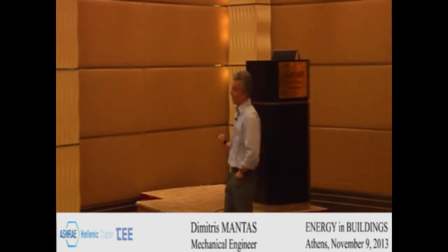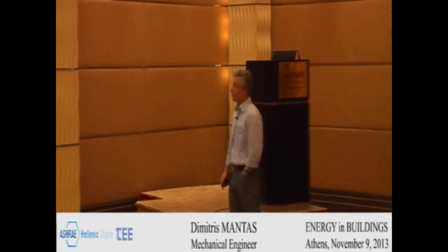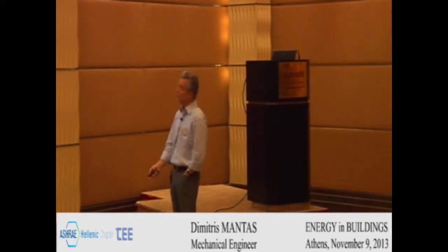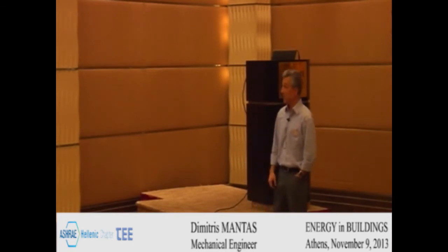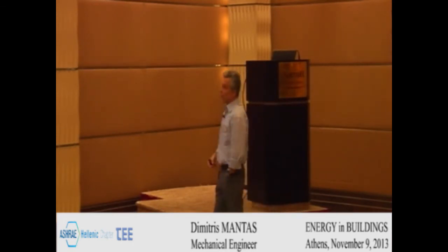Later on, when you see the ASHRAE standards, you will see that they are stricter as far as cooling is concerned, while the European standard 15251 is stricter as far as heating is concerned. They want to maintain high temperatures in the winter. The 15251 is the one we have in the regulation in Greece, but for air-conditioned buildings we are in category 1, whereby we need 26 to 26.5 degrees in our buildings.